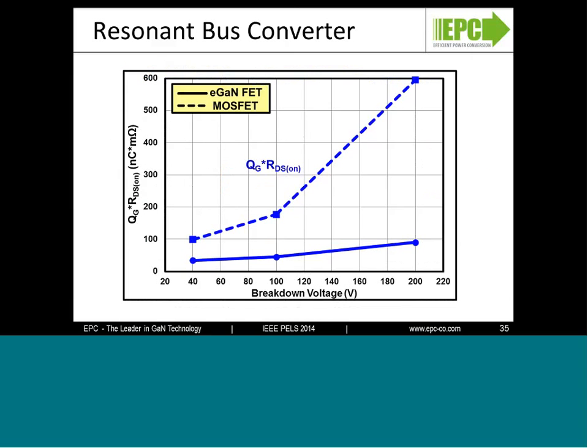In a soft switching application, the requirements of the switching transistor are much different than hard switching. In hard switching, we wanted to minimize our Miller charge, or QGD, and we wanted to minimize our current transition charge, or QGS2. Well, those losses are eliminated by techniques of zero voltage switching and zero current switching. But in soft switching and resonant applications, no longer are those the important parameters. Now we must focus on the parameters that induce loss in these topologies. And the key one is gate charge. Despite the resonant topologies, we still hard switch the gates almost always.